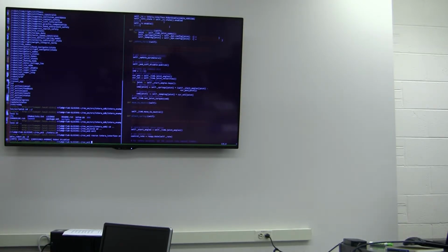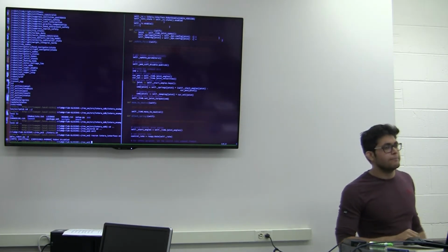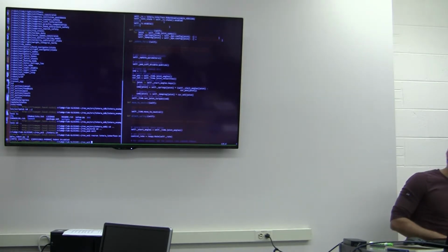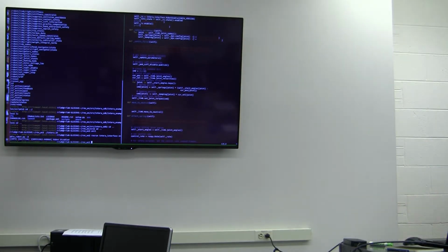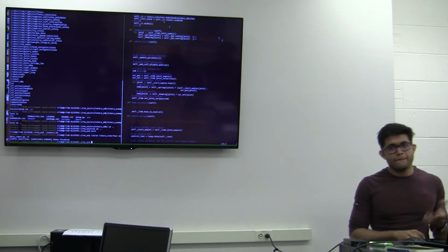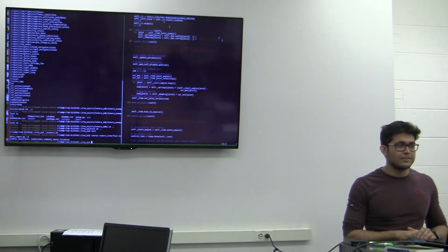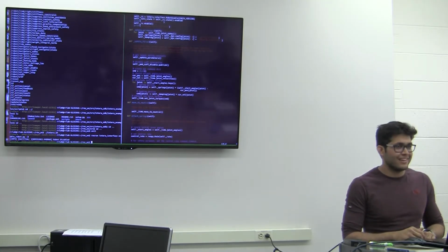Don't hesitate on pressing this button, but we don't want anything else to be messed up. You can always configure the robot again. Right now it's not deconfigured because it was disabled, but always make sure to press this button if you face any issues. If you think the robot is going out of control, just press it. It's a general rule for all robots. Don't just keep on saying, oh, let's see if it hits it.